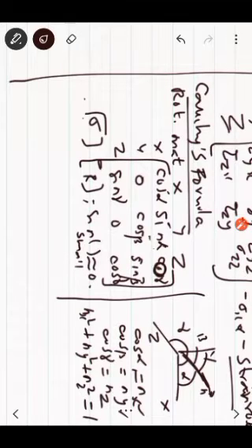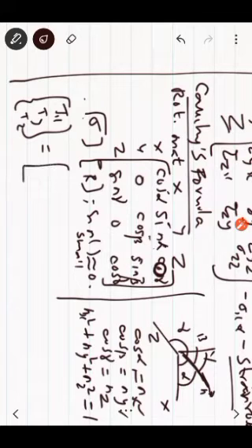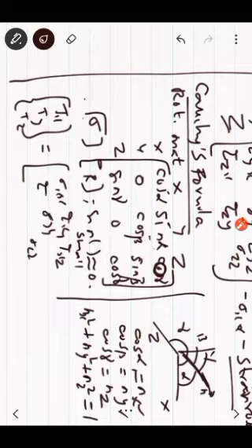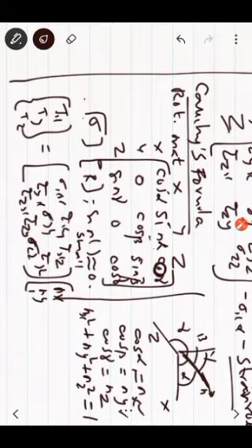If you write only the cos values, you can write the resultant vector along x direction, along y direction, along z direction, is equal to the matrix sigma xx, sigma yy, sigma zz, tau xy, tau xz, tau yx, tau yz, tau zx, tau zy, into nx, ny, nz.